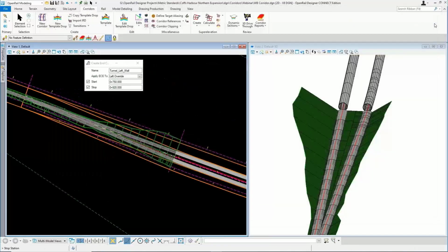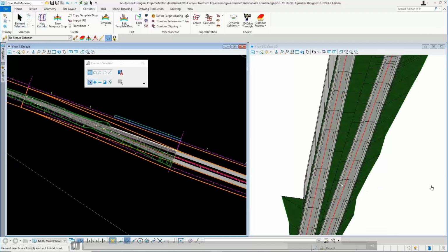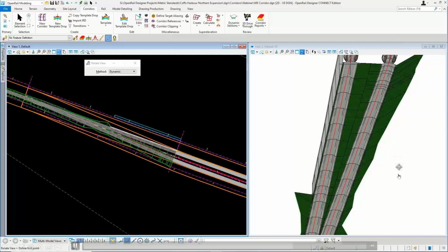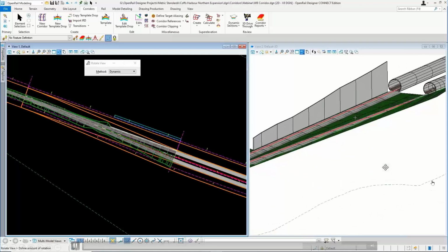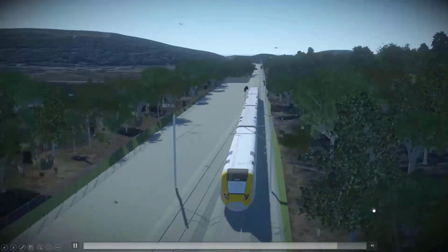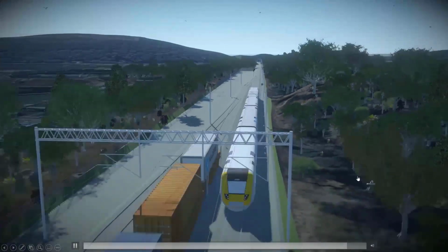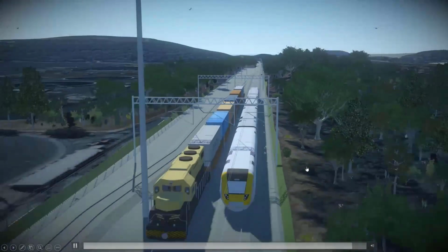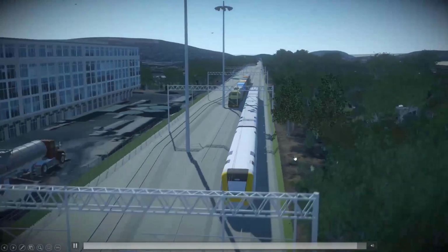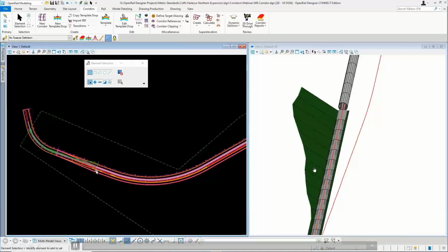It is more optimized to apply a retaining wall instead of having a very large cut in your proposed model. Then output that into a nice visualization with a single click of a button, by clicking the Lumen RT button in the software, so that you can create a nice animation such as this sample I'm showing you.